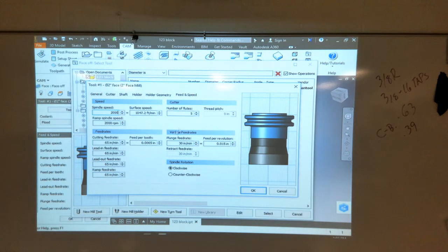I've got 5 inserts, that's right. If I want to stay even lower than that, I can customize this how I want to go with chip load. So maybe even 1800 or 2200. Let's go 2000 just on this one, just to keep it clear.